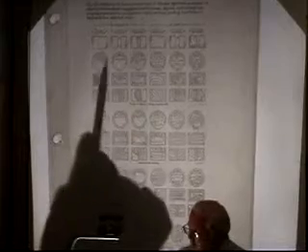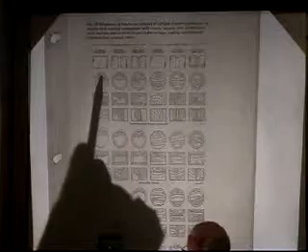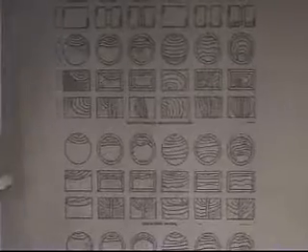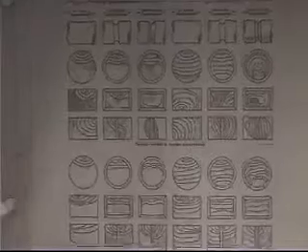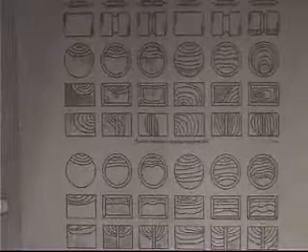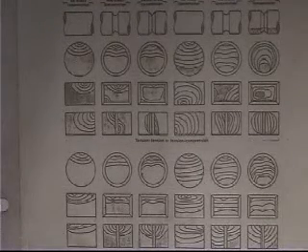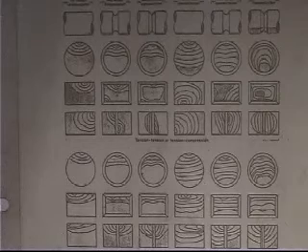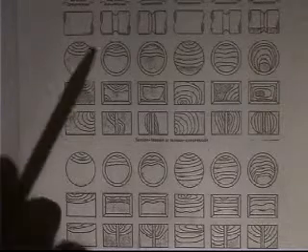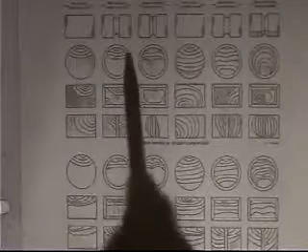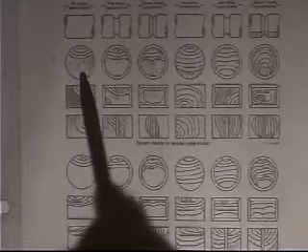If the final fracture area is large, so this is supposed to be, these little lines here are called the beach marks. As the crack grows, it will leave behind, just like a tide going out will leave trash up on the beach. Okay, it'll leave these little marks behind, or the tide going out will sometimes leave ripples in the sand. Most of the time it's smooth, but it'll leave these beach marks. And so that's the region where the fatigue is. There's a different texture there than the final overload.